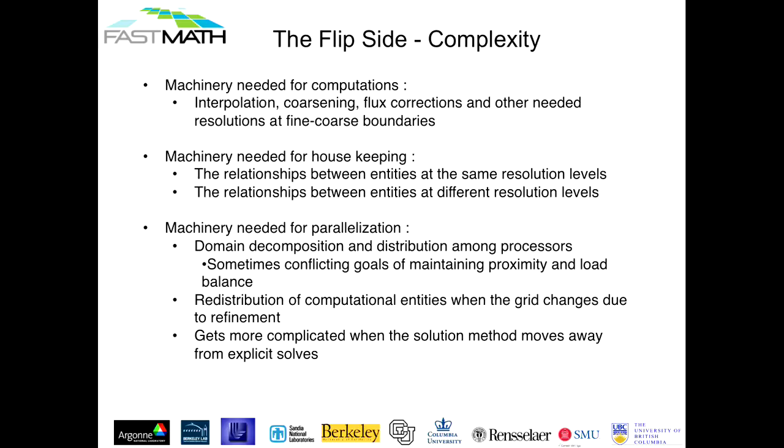So conservative fourth order schemes that walk off the edge of the patch have to still be conservative, have to still be fourth order. So Godunov's theorem tells you anytime the grid spacing changes, you will lose an order, but you will do so locally. So at an embedded boundary, at a coarse fine boundary, in the truncation terms sequence, it is unavoidable to lose one order in your truncation accuracy. So you try to make sure that when you do your mesh generation, the coarse fine boundary isn't where something important is happening.